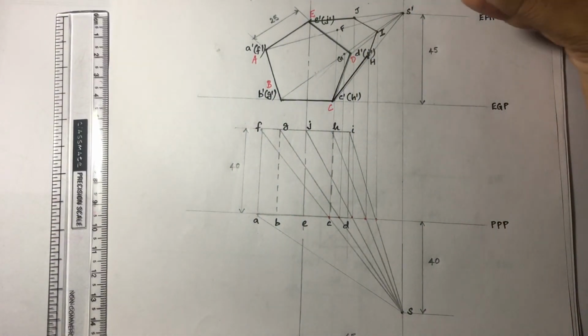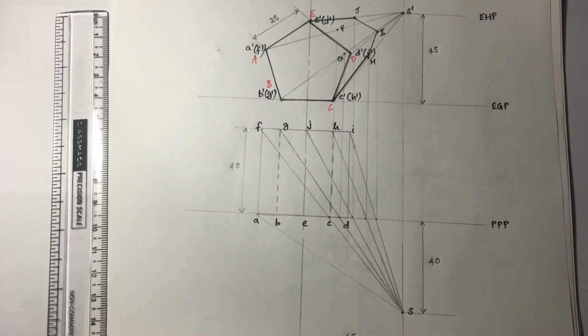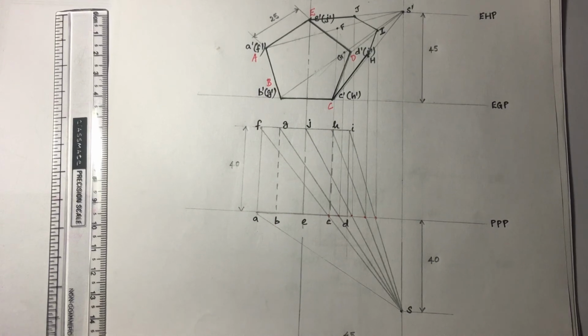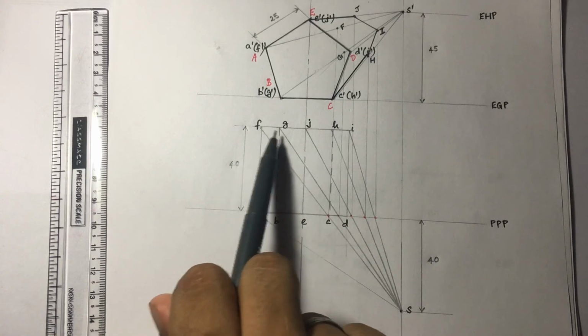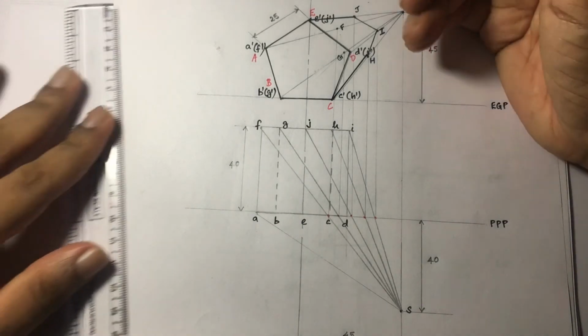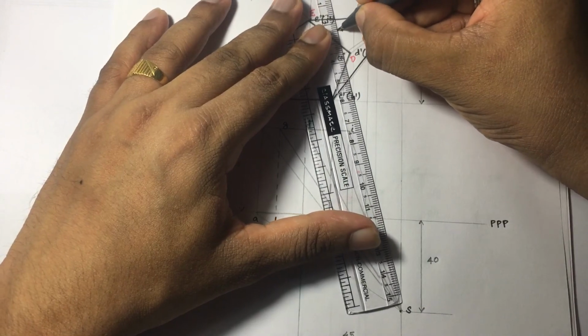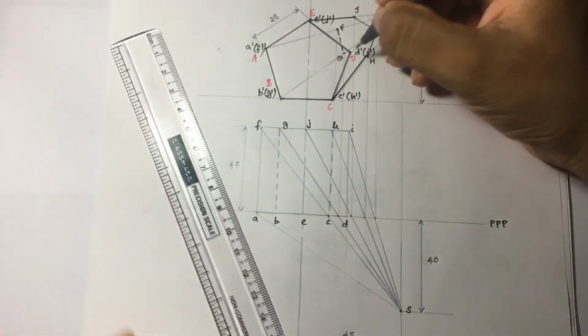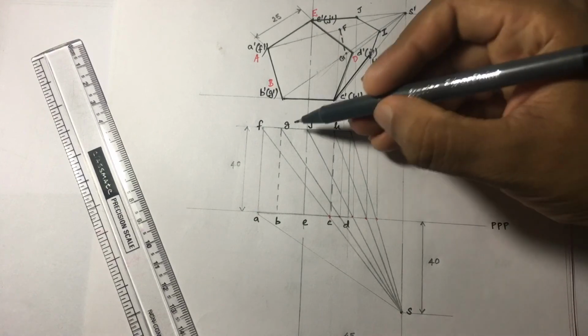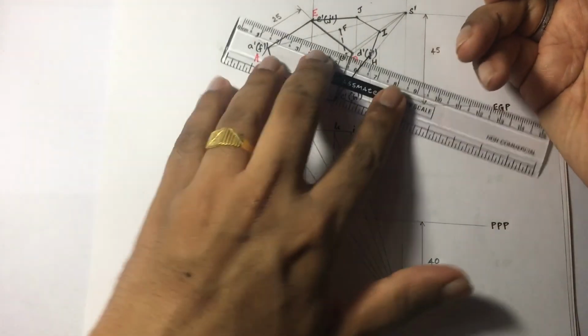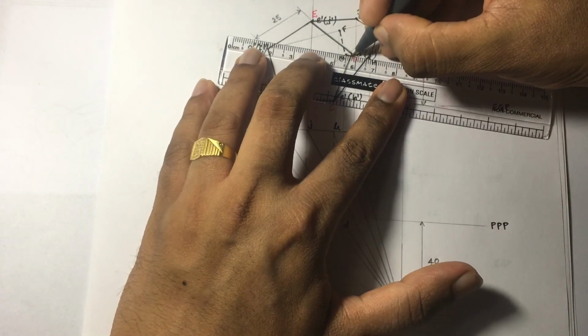Next, you have the point which is G. Okay. From G, you have two different lines, towards GF and towards GH. So first you are looking for GF. For an observer who is looking from here, GF is far away and that is not visible. So GF is to be drawn by using dotted lines. Then GH, for an observer from here, GH is also far away, so GH is also to be drawn by using dotted lines.